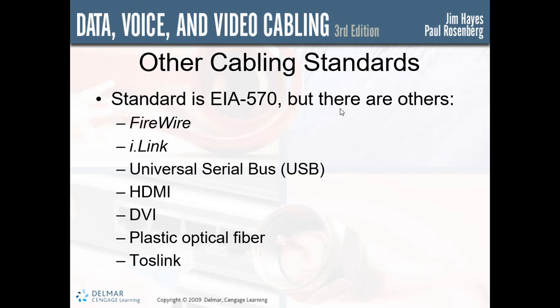It does this with both audio and video over the IEEE 1394 link or system. The IEEE 1394 runs over plastic or glass optical fiber or over short distances of high quality twisted copper pair cabling such as Cat 5 or Cat 5e or better.